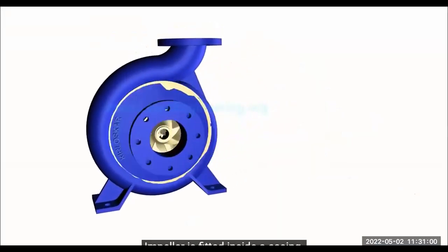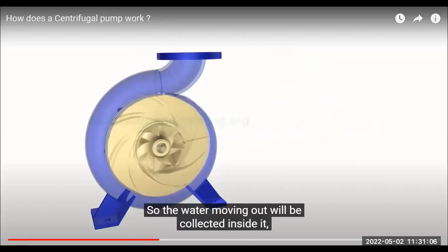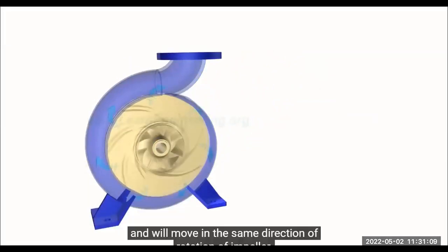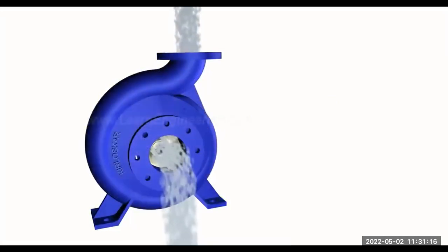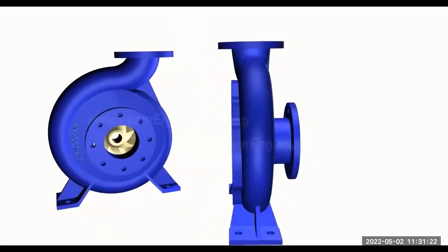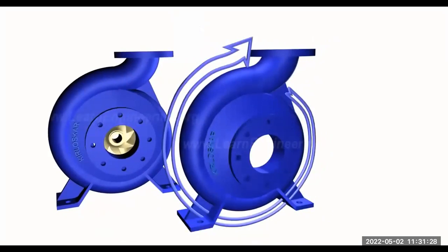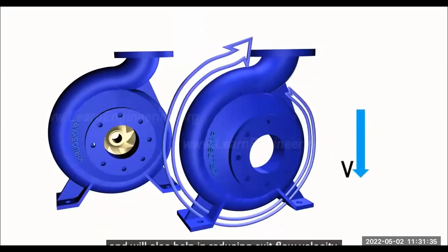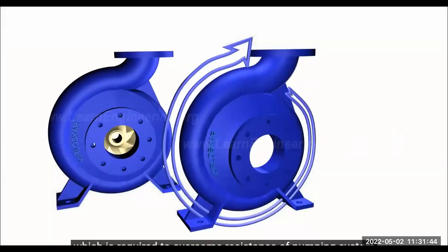Impeller is fitted inside a casing, so the water moving out will be collected inside it and will move in the same direction of rotation of impeller to the discharge nozzle. Here you can note one specialty of casing. It has got increasing area along the flow direction. Such increasing area will help in accommodating newly added water stream and will also help in reducing exit flow velocity. Reduction in flow velocity will result in increase in static pressure, which is required to overcome resistance of pumping system.